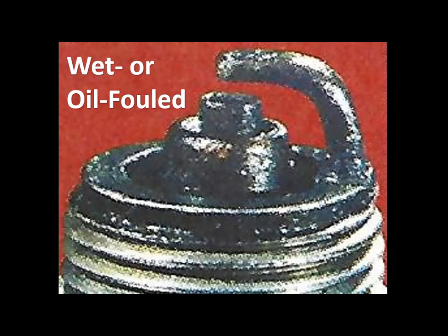The causes of this problem may be worn piston rings or cylinder walls, worn valve guide seals or valve guides, leaking intake manifold gaskets on some V8 or V6 engines, a leaking transmission modulator, or a completely restricted PCV system. This is the positive crankcase ventilation system.